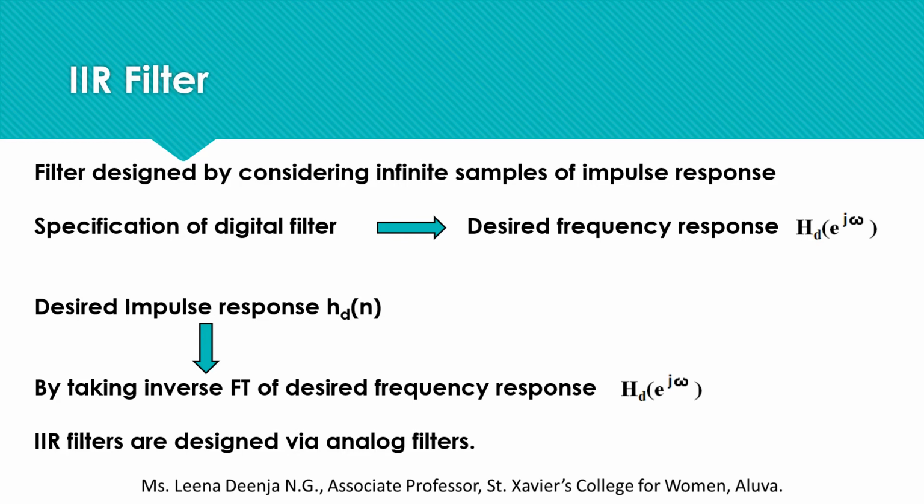In the digital domain, the processing of infinite samples of impulse response is practically not possible. Hence, direct design of IIR filter is not possible. Therefore, the IIR filters are designed via analog filters.